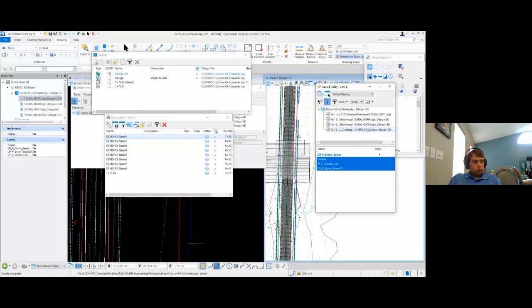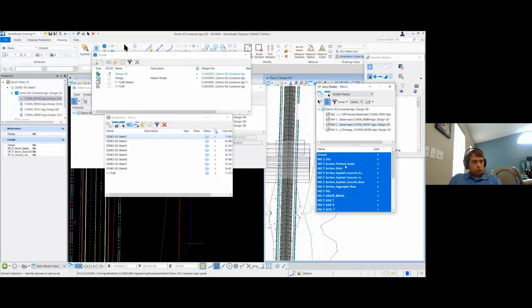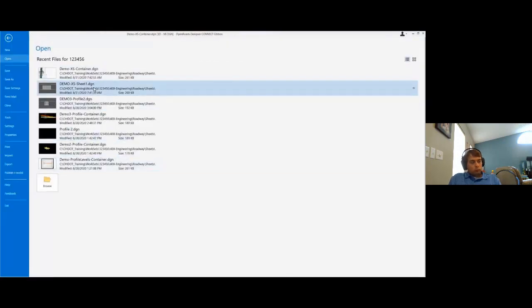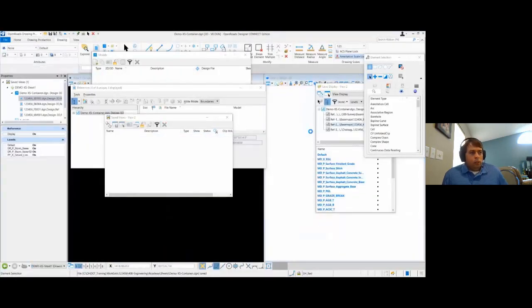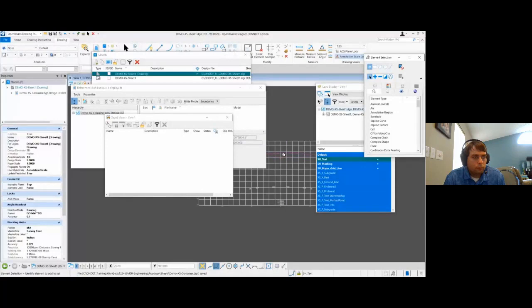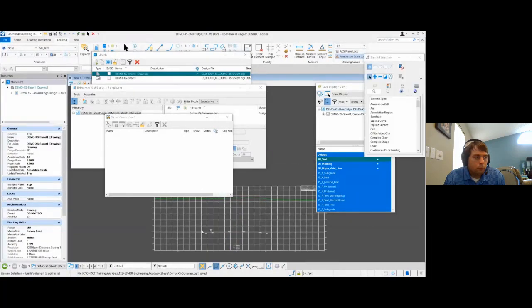So now if I go over to my global display in my 3D model, if I turn off here, I'm turning it off for all my name boundaries. So maybe I also just come here and turn off all these so you can see. So I save settings. Now if I jump back to any of those cross-section files, you'll see that these levels should be off. And a quick look, it does look like they're off.